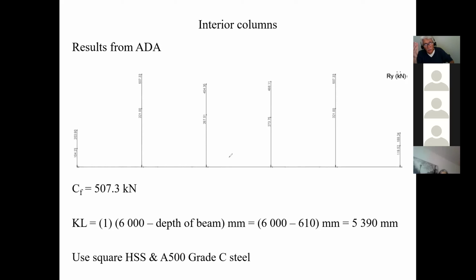In your project, I want to see the BR and show me if the BR is greater than the CF. You understand? Okay. And if it isn't, of course, you just take the slides and you show me the calculations in your design brief. Because I knew that if I left it up to you guys, you would be totally lost calculating those bearings. But now you have an idea of how.